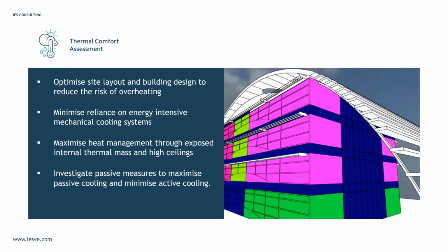And with respect to SI4, managing heat risk, through early engagement the modelling team can assist with optimising the site layout to reduce the amount of heat entering the building by assessing orientation, shading, and fenestration choices. At concept stage, through close engagement with the entire design team, modelling can be used to investigate the provision of passive measures to control overheating alongside mechanical ventilation and ultimately low energy cooling if this should become necessary.